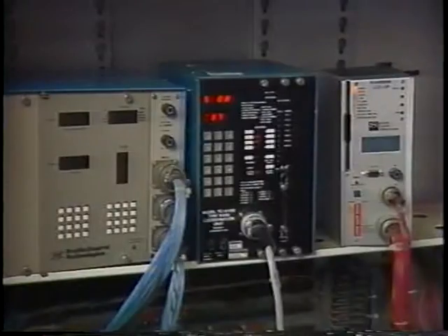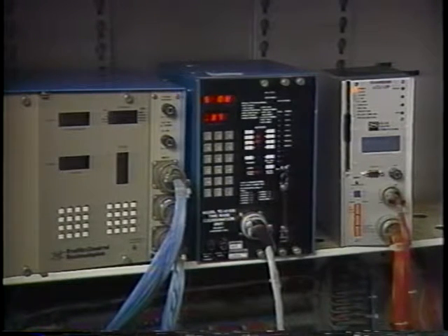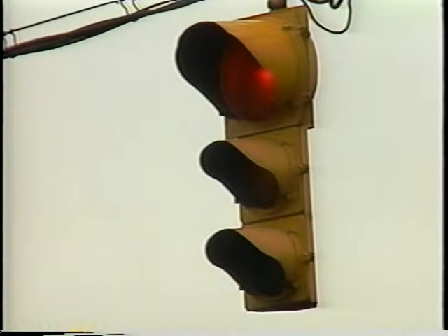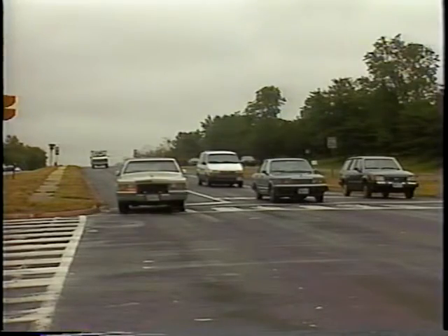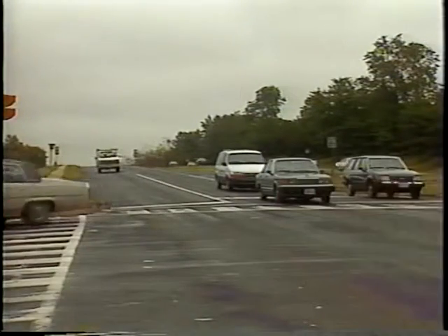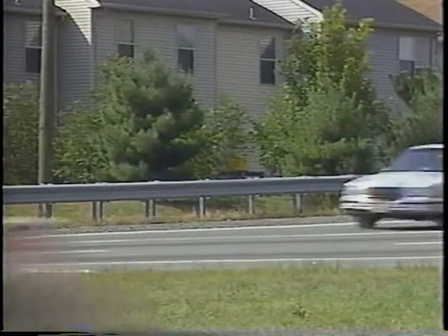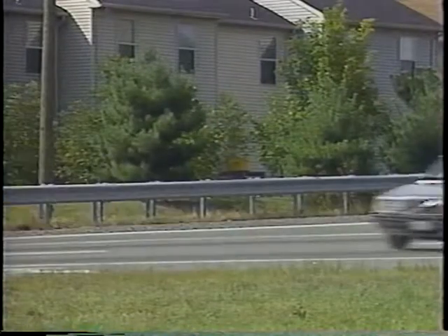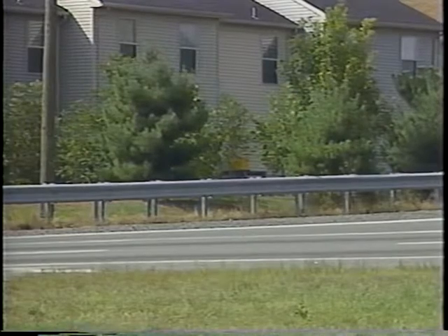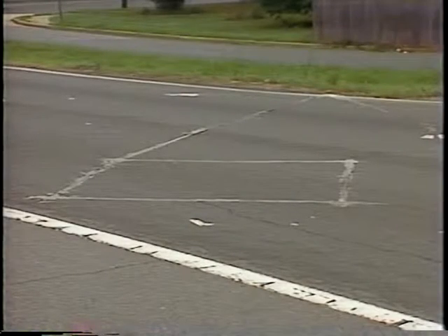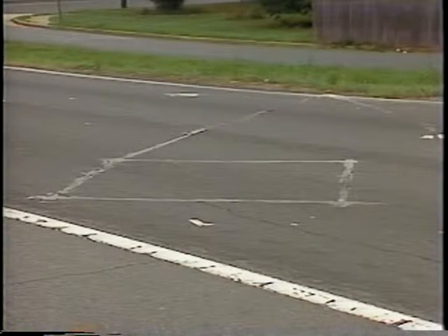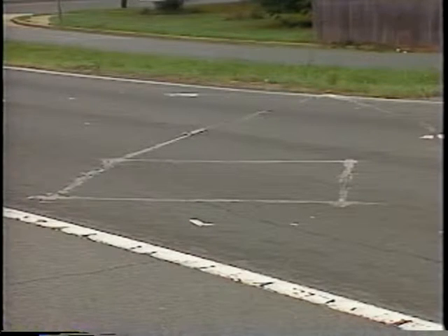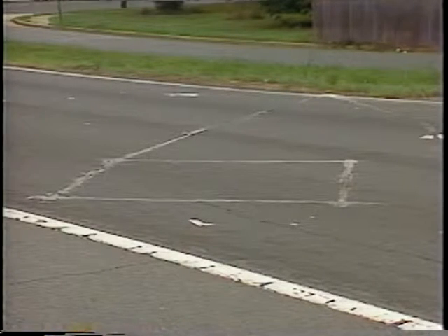This locking feature allows a vehicle call for green to be remembered or held by the controller until the call is satisfied. The call for green is remembered even if the vehicle continues past the detection area, such as a car turning right on red. In the non-locking mode, the controller forgets or drops the waiting call as soon as the vehicle leaves the detection area. Locking detection memory is associated with small area or point detectors, such as a 6x6 foot loop detector.